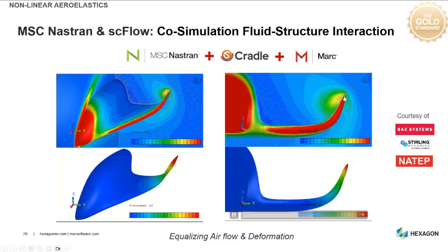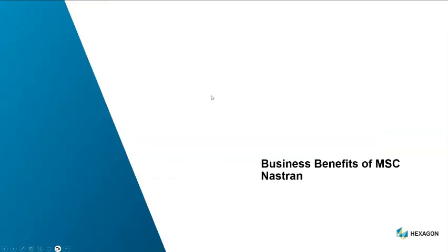There's some examples of simultaneous analysis, so it may not be that clear. You can see there's small amounts of movement at that location. So this is especially useful in aero for the case where we do not have an infinitely stiff wing, for argument's sake, especially if we want to move towards a lower stiffness wing. In that case, we don't need to model in the final state. We can model our actual wing, add gravity, all of that, and calculate the pressure, and we can see how that part moves. So this can, amongst other things, be used to calculate the aeroelasticity, flutter, and whatever behavior of such a component.